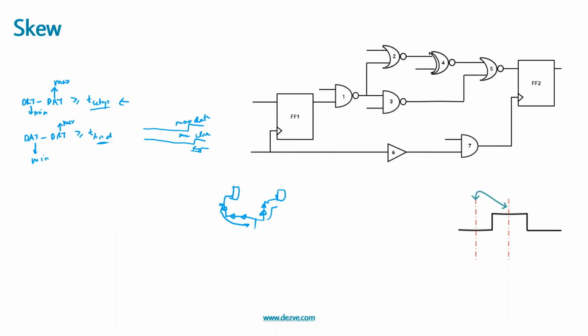The skew would already be actually implemented, and then the propagated clock would be used for that computation. Now for our synthesis purpose, when we have to estimate a margin, suppose we estimate that the clock network can have a skew of 0.5 ns, correct? For setup, we don't want to delay the clock. We want to pull the clock as close to the data and then make it fail, correct? That's our intention. So in case of setup analysis, the skew values are subtracted from the clock path, and then the resultant clock is checked for the setup requirement. Got it?